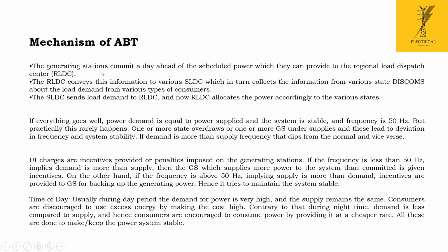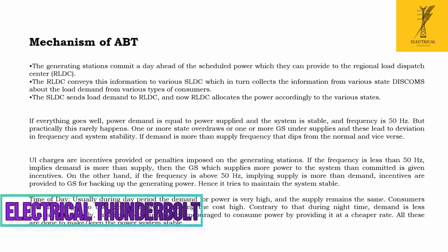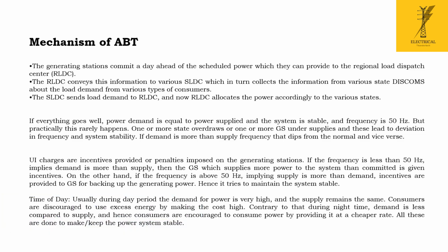The generating stations commit a day ahead the scheduled power which they can provide to the RLDC, the Regional Load Dispatch Center. This RLDC conveys this information to various SLDCs, State Load Dispatch Centers, which in return collect the information from various state distribution companies about the load demand from various types of consumers. The SLDC then sends the load demand to the RLDC,